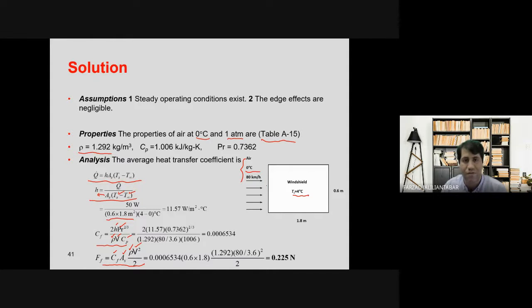But we have heat transfer in this problem, while temperature remains constant. It means all of the power which is being used here, that 50 watts, will be transferred by heat transfer to the air. So we have a steady heat transfer actually. So the Q dot here will be 50 watts. This is the point and note which you need to know in this example.